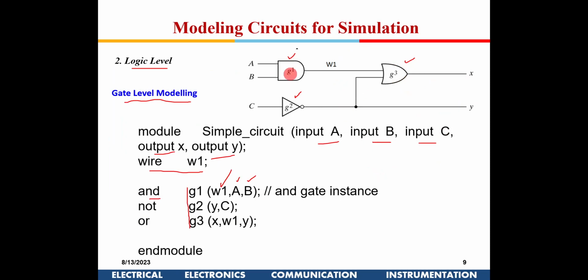Here also optimization is possible, because if you see the actual tools, the fab library will give you different types of AND gates also: slow AND gates, fast AND gates. A gate operating at a higher speed will have more current carrying capacity, so higher current and dissipation will be there. So that kind of trade-off is there.